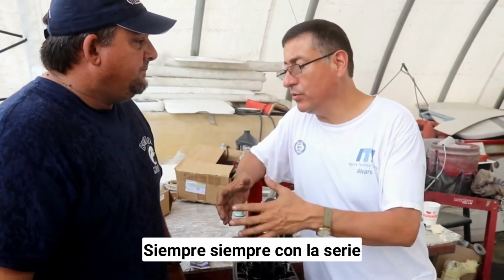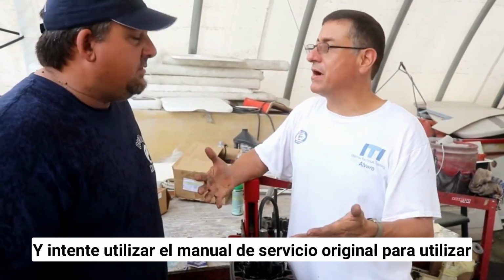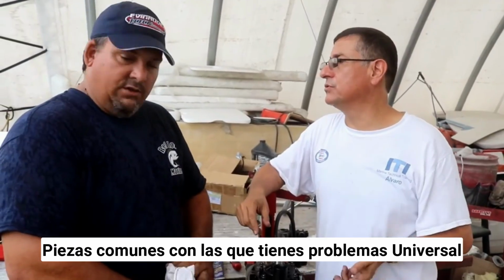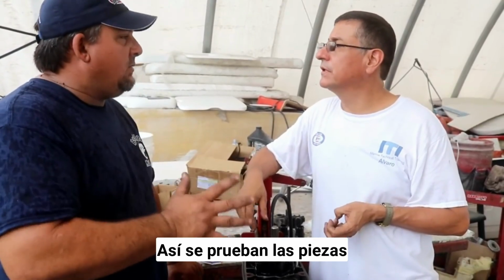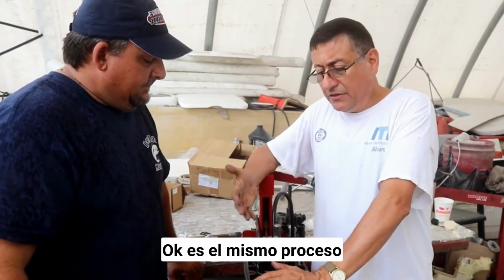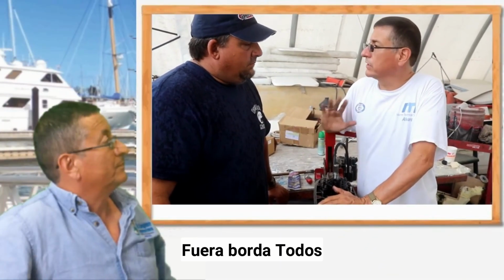And always go with the serial number and the part number. Absolutely. And try to use original parts. Use the service manual. No generic parts, because with generic parts you have problems. Correct. Sooner or later, generic parts have problems and don't last as long. These engines were all tested with OEM parts. That's how they guarantee that it's going to work the way it works. Correct. This is the same process for a stern drive and an outboard. Yep. All right.